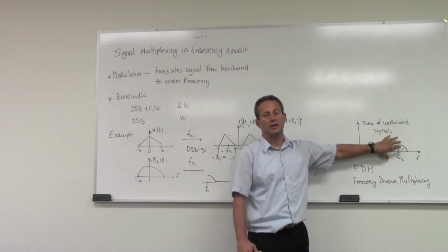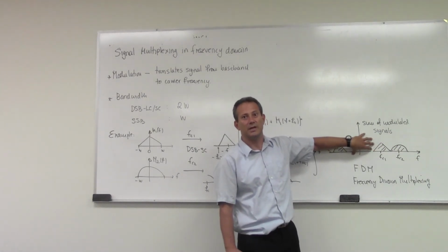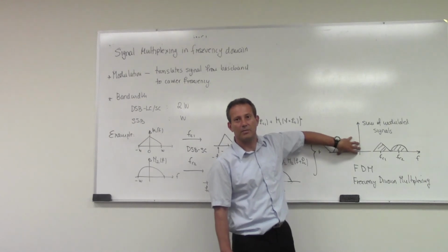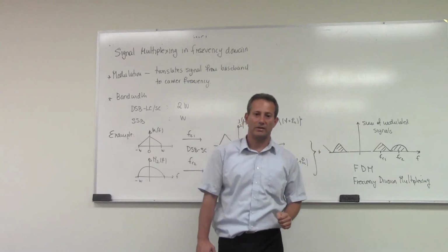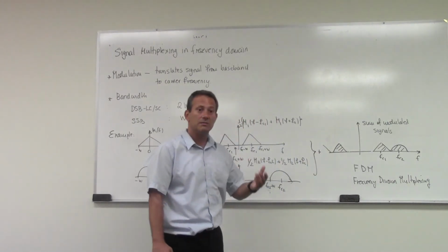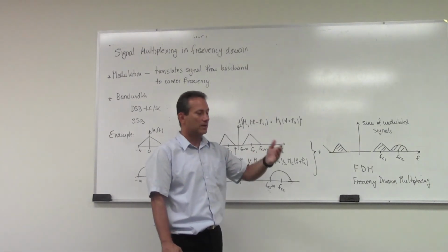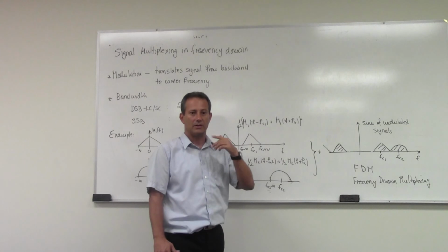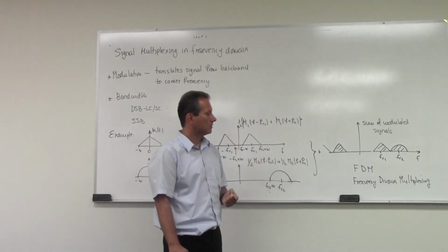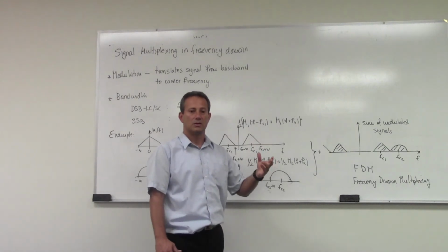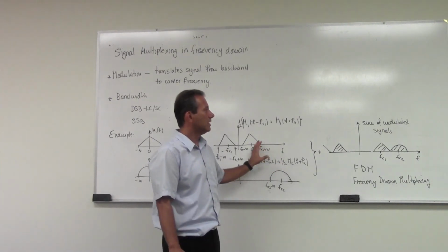of this signal. And then the next one over would be 89.7, the next 89.9, 90.1 and so on. So this is how all of our radio broadcast is stacked. The same thing happens with the broadcast television. Usually the frequencies are a little bit higher, with broadcast FM radio at around 100 megahertz, with broadcast TV around, let's say, 500-600 megahertz. So that's where the TV stations are.